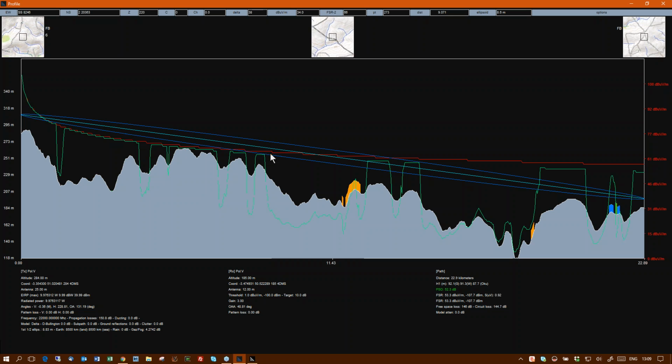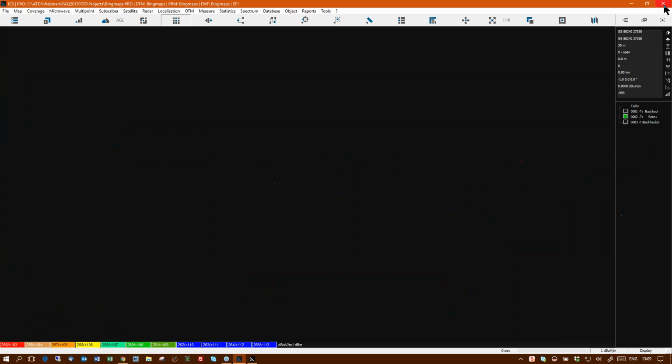So what you're seeing along the top of these flat bits is areas where you are line of sight with the base station, so there's only very little attenuation. But you get big dips. If you go down here, you lose the base station altogether. And as you go back up again, the signal comes back up. If the signal doesn't come back up, you're using a coordination propagation algorithm like 1546 or something like that, which is utterly inappropriate for this sort of work. That's for coordination work. You wouldn't want to use it for detailed radio planning.